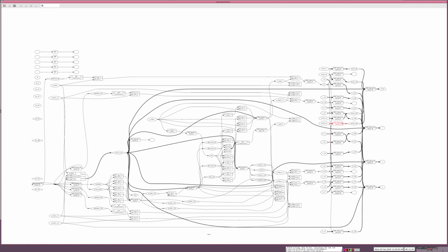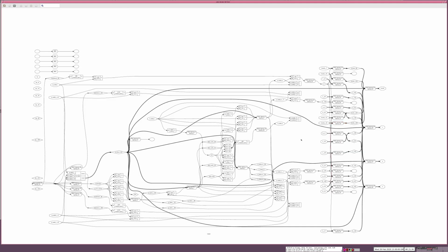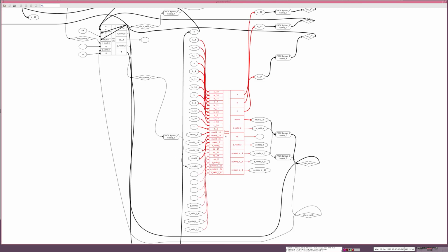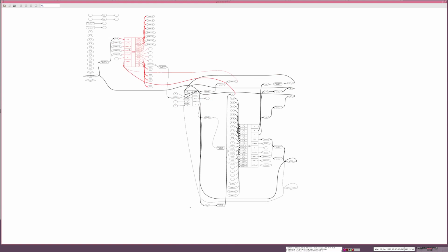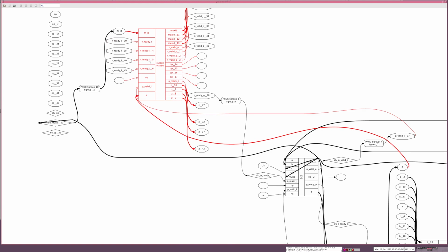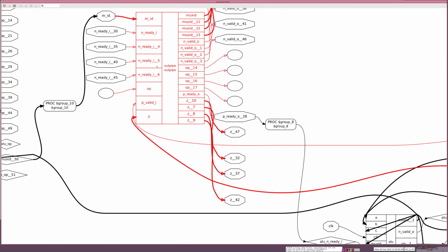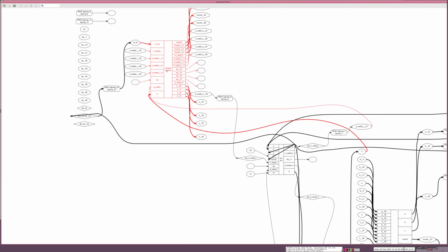Where is it? Yeah, here we have the latches for A, B, and C. So it's a synchronous block, passing its data across with ready and valid signaling. But we need only one of those to go through at one time. So that's your input selector between 4 in, 1 out at a time, going to the ALU, and then it goes back to the output, so that you can fan out, so that it can store those results in the output, and they can be selected, ready to go into the register file afterwards without losing the data.